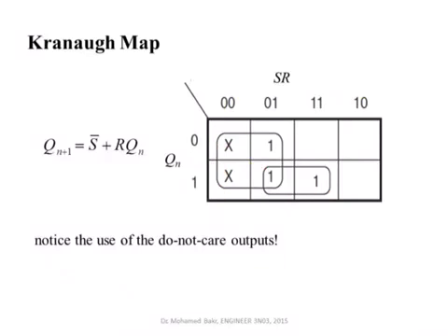Forbidden means that when I design such a logic circuit, I'm not going to allow this situation to appear. So I can take it as a do not care. Do not care means I can take it in my Karnaugh map as either 0 or 1. So you can see if I make them equal to 1, this will help me lump or group these 4 together to create a much simpler logic table, or much simpler implementation of my logic circuit. This is why I'll take them as 1 and 1.